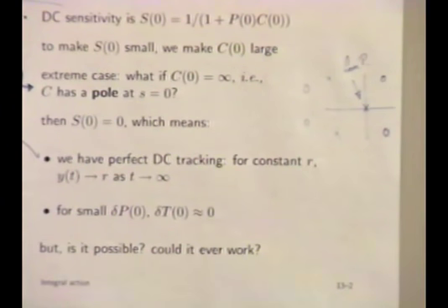You can also think about it this way. When you put a pole at the origin, you're effectively adding some kind of delay to the system. And delay in the context of feedback, remember Boyd developed this intuition in previous lectures, can very easily lead you into instability.